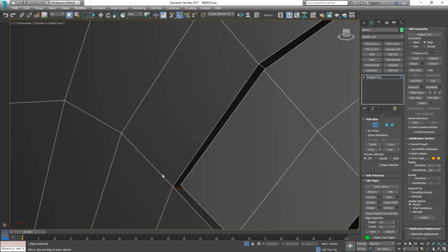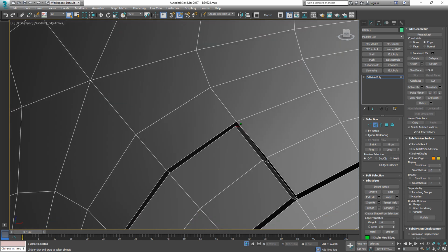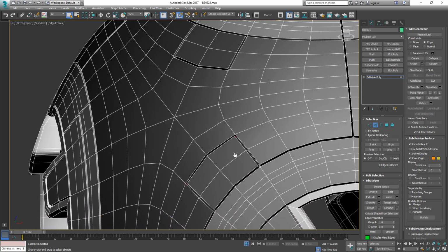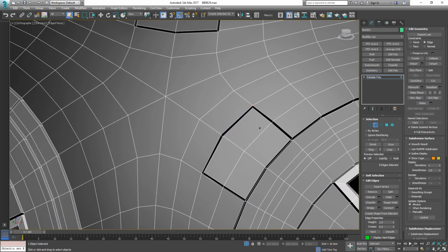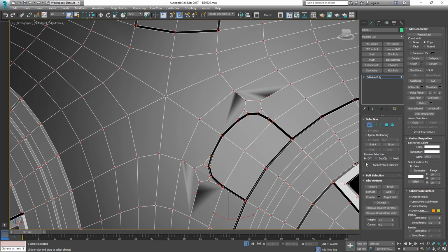Once we perform our chamfer operation, so double click on that. And now with these 8 edges in total, we can bring up our chamfer window here, not the modifier, but that tool. And we're just gonna increase the amount here so that it's really nice and round. So let's confirm that. And now we have a bit of a mess here. So while being in edge mode, let's just select these 2 edges, collapse them, and do the same thing here on the opposite side.